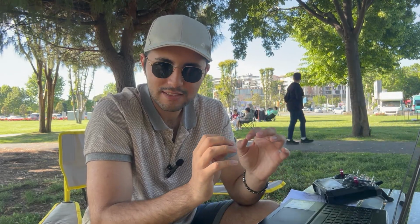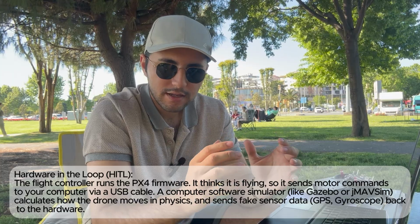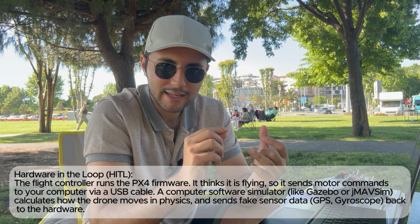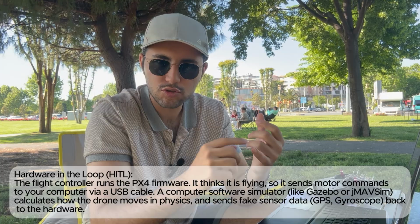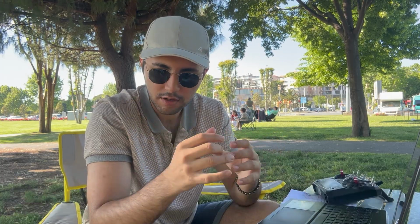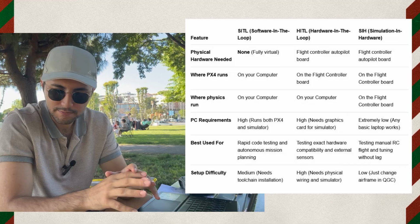So I know this might sound confusing, but I'm just going to say it very briefly and simply. In HITL, hardware in the loop, the configuration files and airframe geometry are coming from the flight controller, and the sensor values are all coming from the telemetry from the flight controller itself. In software in the loop, there is no connection whatsoever to the drone itself. These are basically the examples that you do from the PX4 documentation.